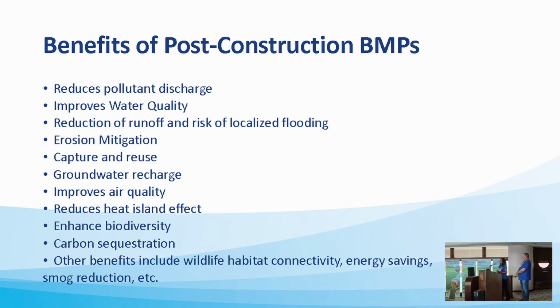So besides MS4 permit requirements, why should we do these post-construction BMPs? I know the previous speakers have reiterated that there are a lot of benefits of post-construction BMPs. Primarily, they include environmental benefits, which are listed here, but they can also be social and economic benefits. For environmental, the obvious one is that we're going to provide water quality. We're going to reduce the runoff and reduce the risk of flooding.